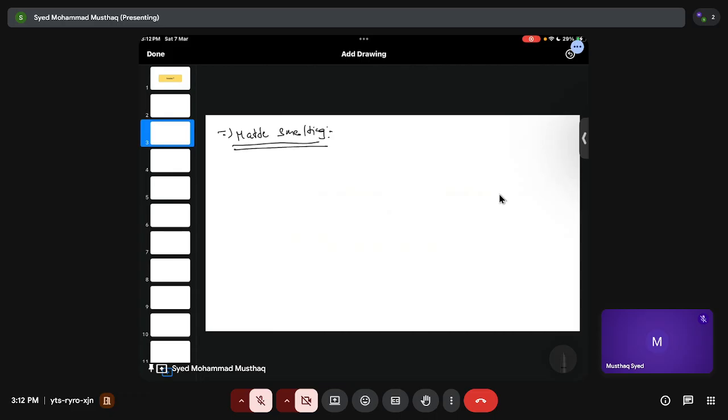Now matte smelting is nothing but your mixture of sulfides, right? So slag is nothing but the mixture of oxides, and there might be some minute amount of sulfides, selenides, silicates. So matte is mostly sulfides. We call it matte if it is a mixture of sulfides.